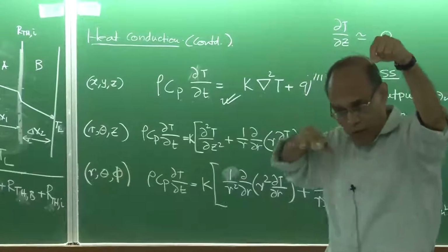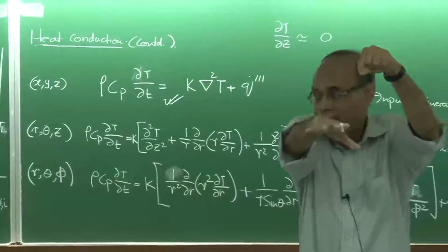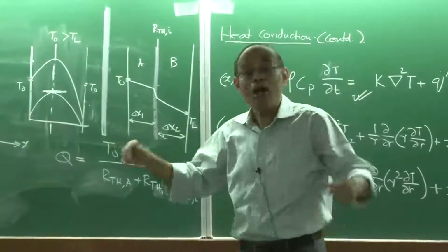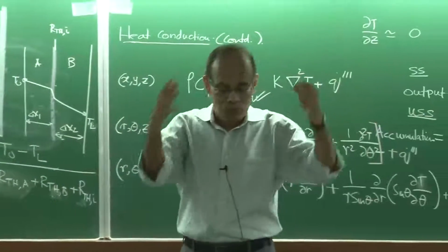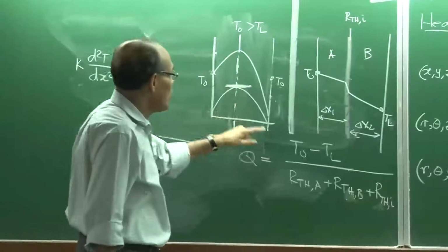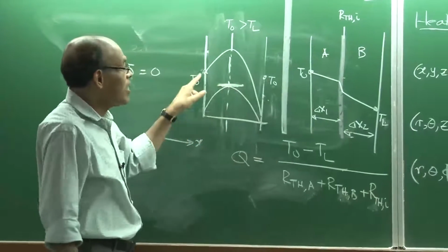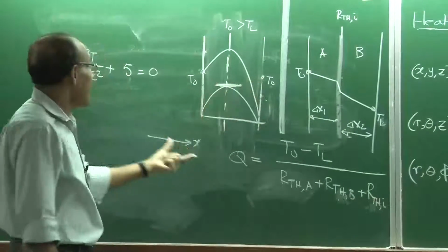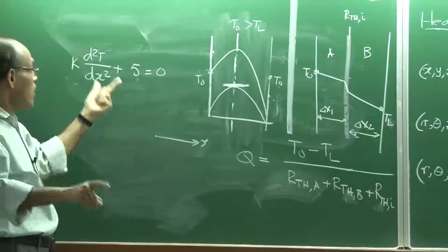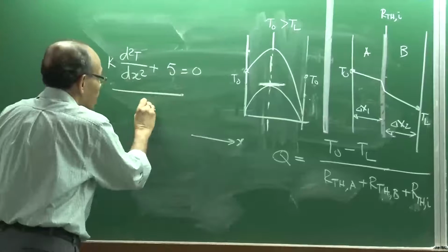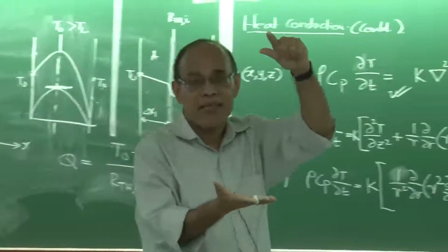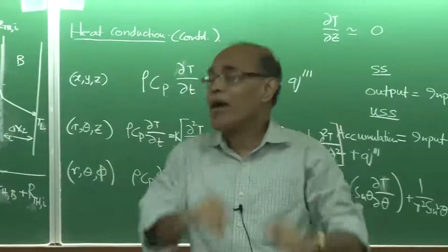Between the flat plates, flow is taking place because of the pressure gradient, same as in the cylindrical pipe. There we have seen that the flow profile becomes a regular parabola. So, in this case also, if these temperatures are identical, this problem becomes, in the Cartesian coordinate system, absolutely identical to flow between two parallel plates driven by a pressure gradient.